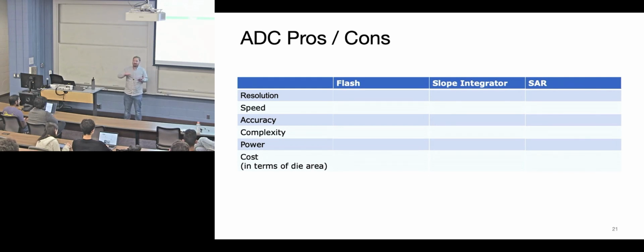Well, as you make your resistors, the fabrication process does not inherently make things exactly the same. One step is you go and polish the die while you put the next layer on, and that will unevenly take off some of the resistor metal or the poly resistor, whatever it is, on the edges of the resistor bank, and those resistors will have slightly different resistances. Not that you should remember that, just know that because you put a resistor down doesn't mean you get out the value, and there are some inherent reasons why it might not be great. But in this case, it's pretty good.